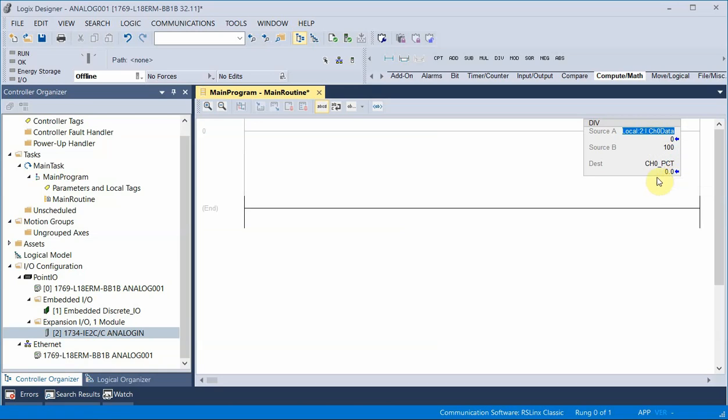That's it. If I want something else, like if I want to know what the actual milliamps the number is, and I've got to do something else. Like I could go back to a 4,000 and 20,000 and divide that by 1,000 and get 4 to 20. So, there's many ways to do this. They all work well. All that's left for me to do now is to download this to a target system with a module on it, and it should start to work.